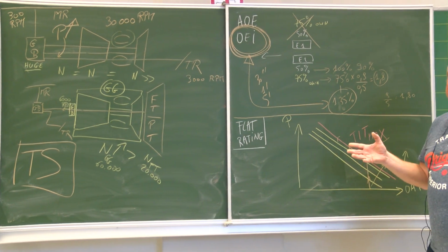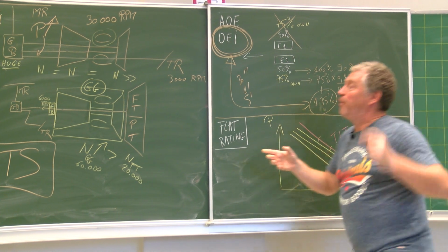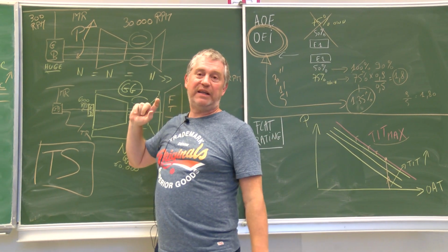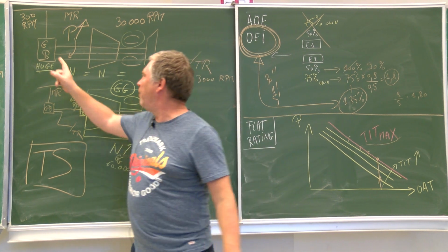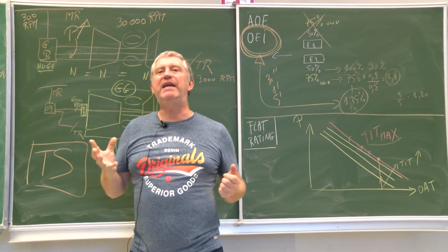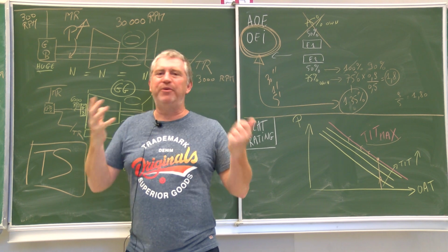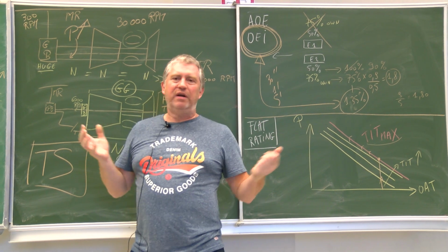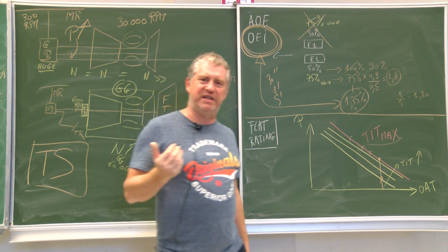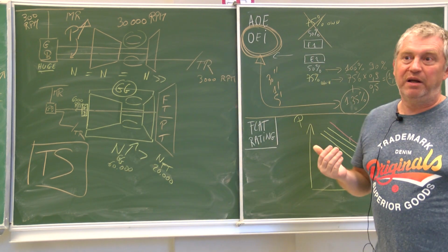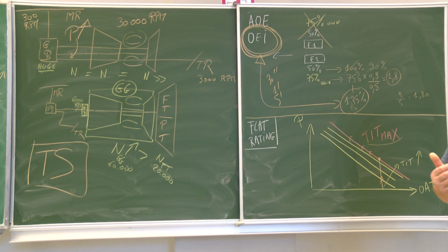And what is then the solution? You could say, I will increase the diameter of the shaft so that it is not taking place. I will use heavier teeth, other material, larger thickness of the teeth, I don't know. So to avoid the situation, to avoid the danger. But then the engine will become heavier. And this is something that you cannot afford.